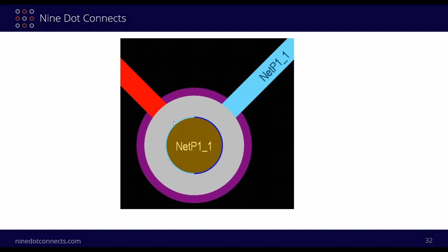But what they did over here is you can see that this color band here, which starts on layer 5, and then they have the dark blue color band, which is layer 8, which is the traditional bottom layer color there. And so now I know this has been back drilled.